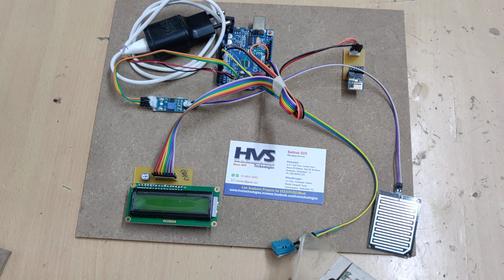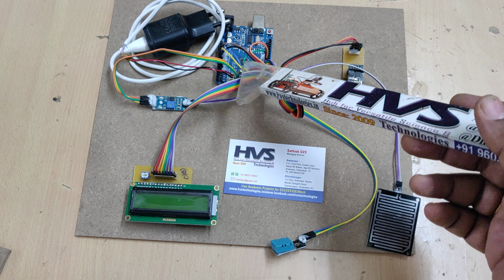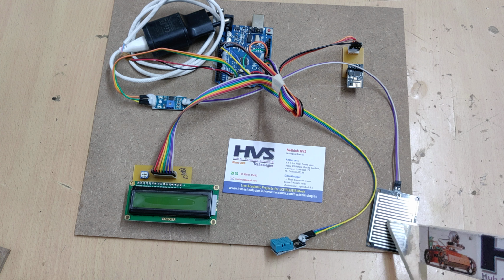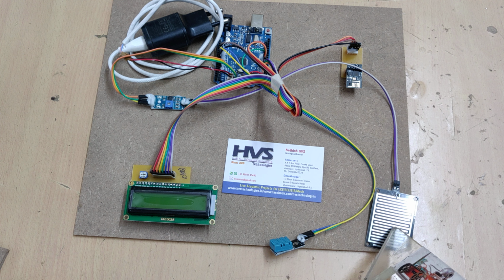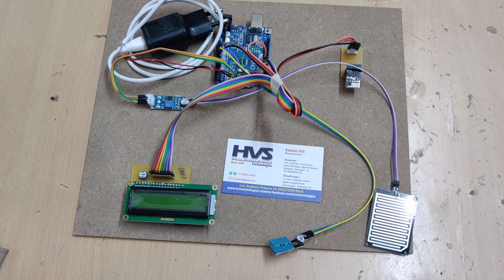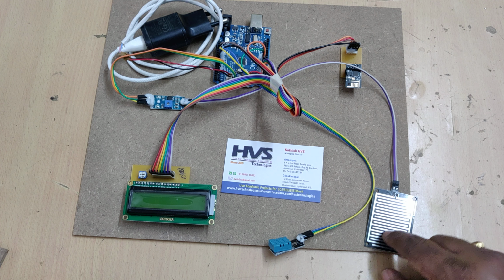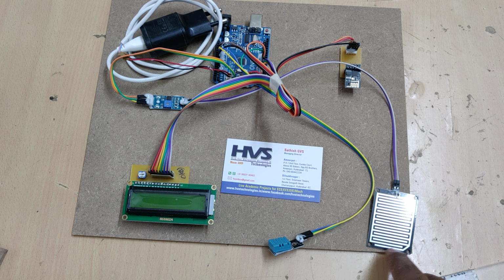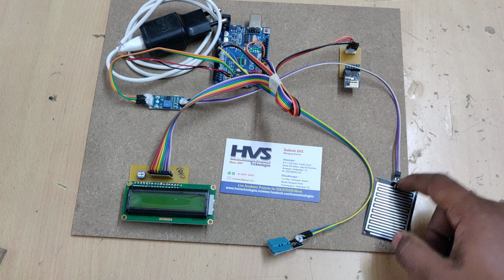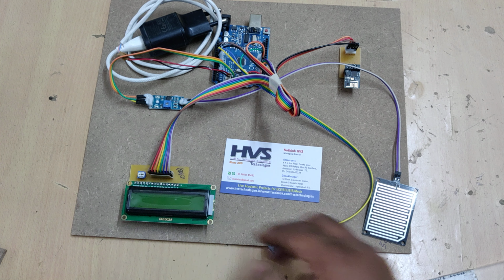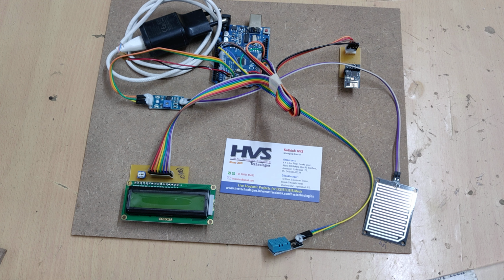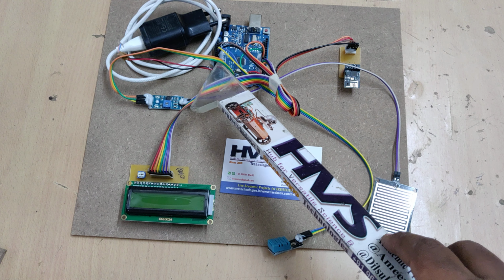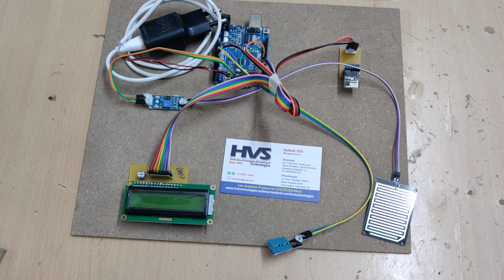In this one we have interfaced the DHT11 directly to the UNO board, but the rain sensor module is interfaced to the UNO board through this amplifier, as we get a low, varying voltage when we place droplets on these plates. As we can see, the two side-by-side electrodes are connected directly to the two pins and then to the amplifier. Whenever a droplet is placed over here, the voltage is in millivolts, so that will be converted to between 0 and 5 volts, and that is the main input to the A0 pin of our UNO board, which is an analog input pin.